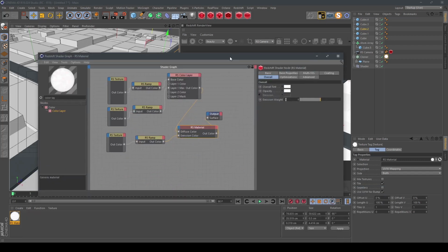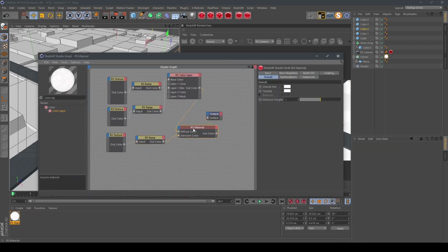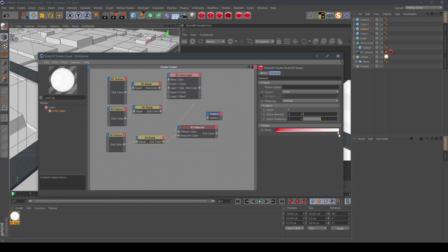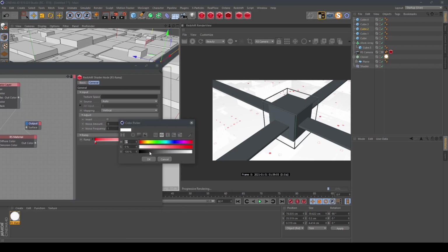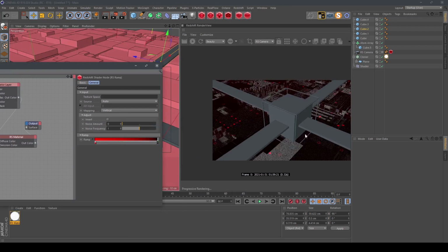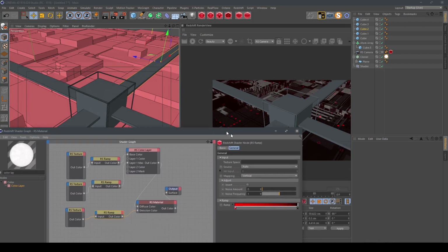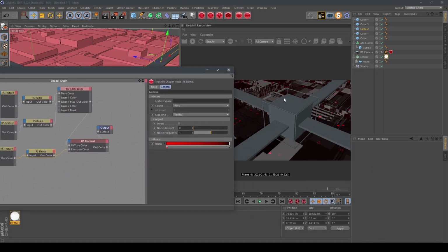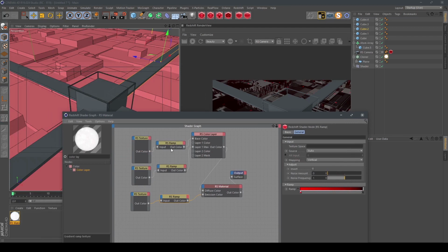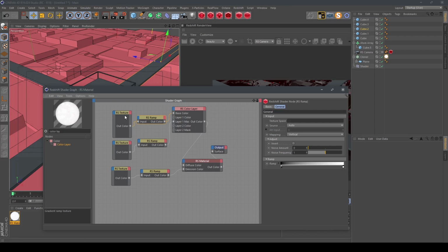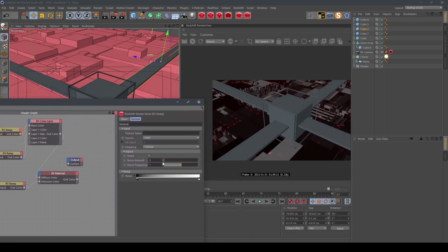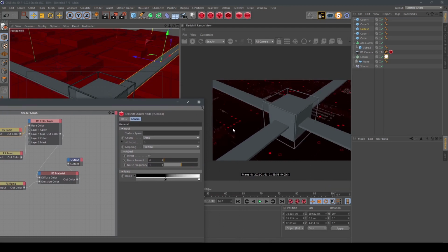It's totally white because our emission color is set to white. We need to set it to black here, and also there is too much white texture here. We need to adjust the ramp. Go to the first one, this ramp, and resize the black color. To see it better, let's create a dome light.